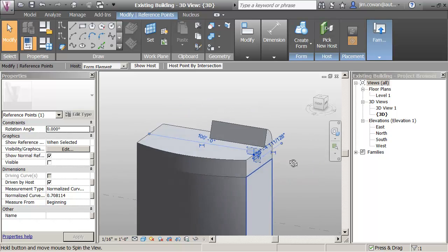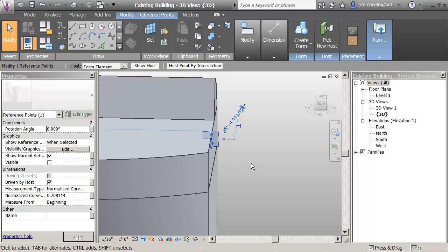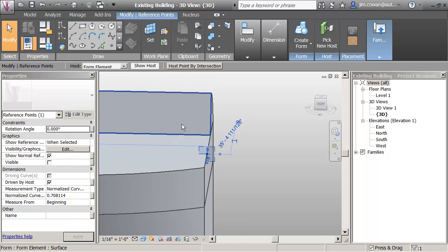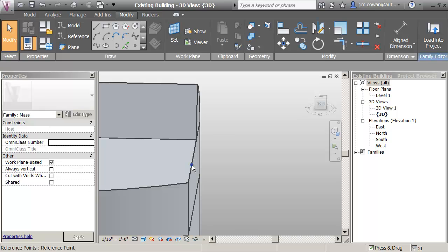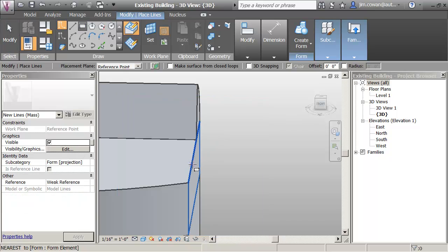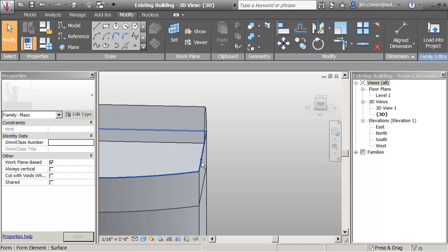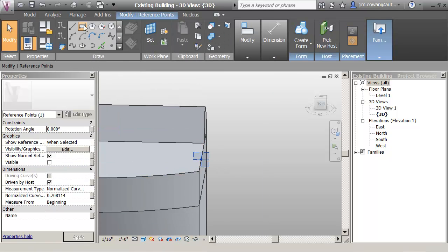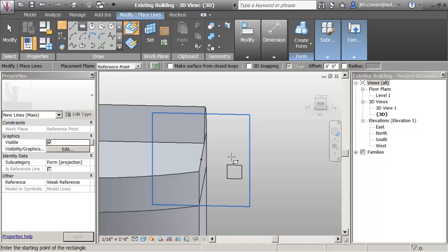Now a technique that I find useful is this: sometimes when you've got multiple faces and you hover over them, it wants to change the orientation of the face that you're drafting on. So I find it sometimes easier to make the face of the point active and then draw the sketch that I want. If I go close here, I might not get the result that I want in terms of which plane it comes in on. But if I make it active, so it's the plane that I want, and then I draw this out in space, I could go and pick that and make it 6 feet by 6 feet. I'm almost there, there we go, 6 feet by 6 feet.